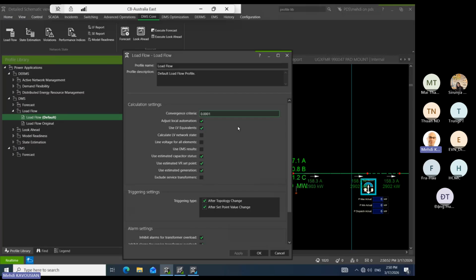It has the load from the load profile, so it multiplies the curves by the average, and then it calculates what would be on the feeder head. But then it needs to consider the losses and stuff like that. So it needs to iterate a few times to get the results. In each step, the error between two iterations should be less than that first parameter.